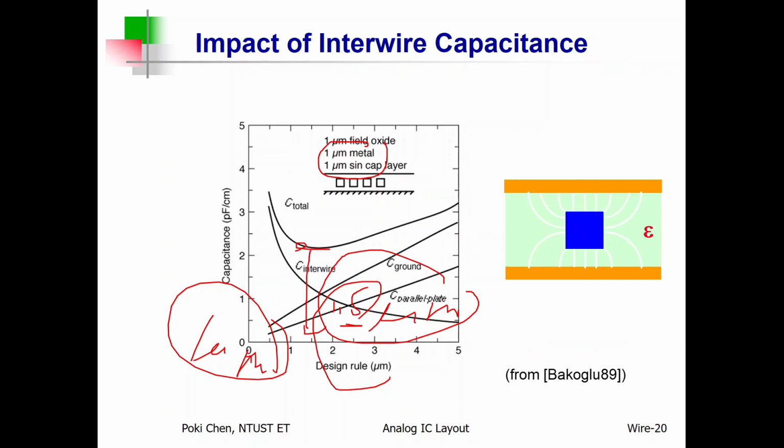But for accurate simulation, especially for RF circuits, if you would like to connect the device in your LNA, I think you had better try your very best to simulate everything accurately to make the final decision how wide the metal line should be.